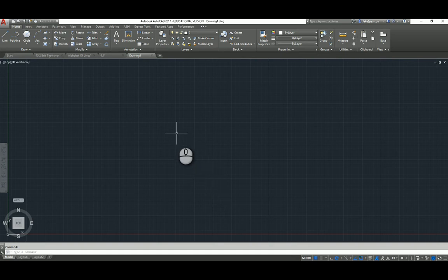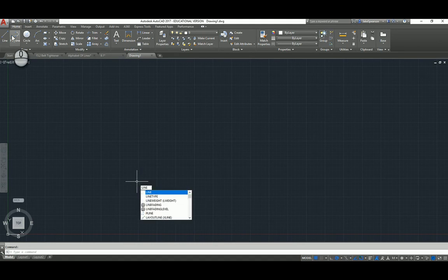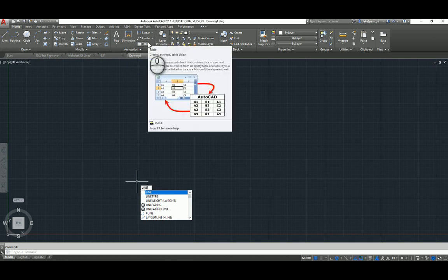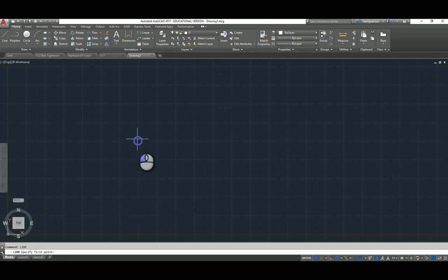Okay, just to verify that we are using dim style, I'm going to draw a line. One thing you will notice in all my videos, I will use the command bar down here by simply typing in commands I'm looking for, rather than searching them out in my toolbar up here, which can be beneficial, but also can slow a person down when in AutoCAD. So I'm going to type a line. I'm going to verify that this is a decimal by looking at the actual numbers. Notice 7.0735. If it was metric, it would be close to 300 millimeters. So I am therefore in a decimal